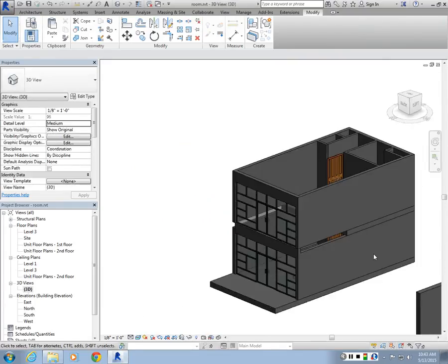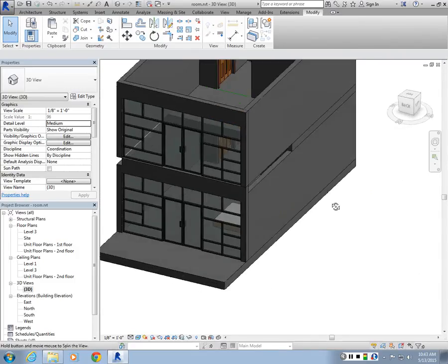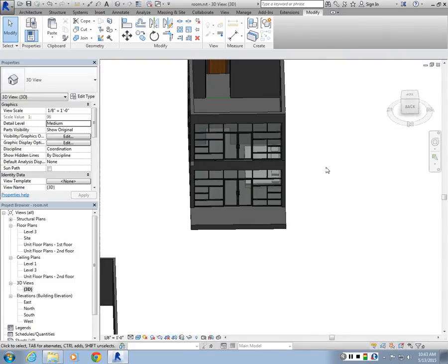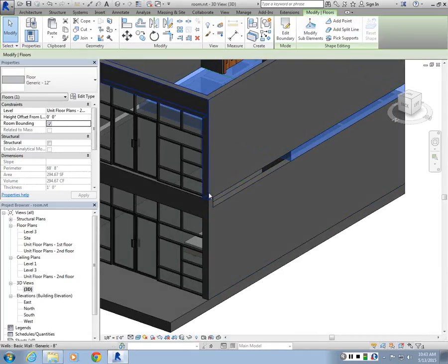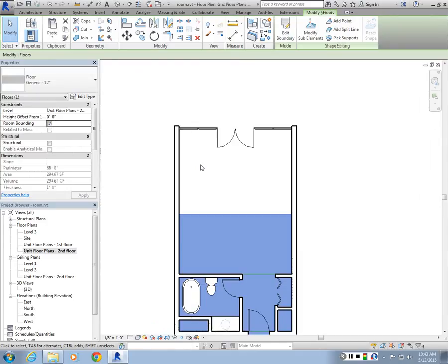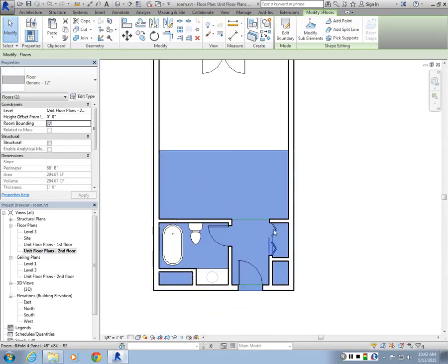And if I look in 3D, my floor is here, right? And technically what you could do is for the second floor, you can keep this offset inside the walls so that this detail is not visible like this. If you want to change this, you can add the slab here. You can keep it as a solid model basically. But the way I normally do it is to keep the floor slab inside the walls and have the walls go up to the floor level, right? And that one we could also do.